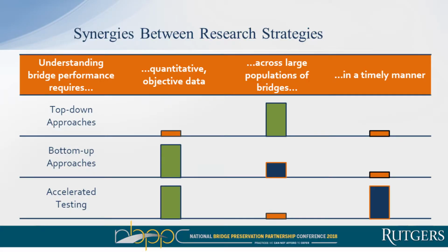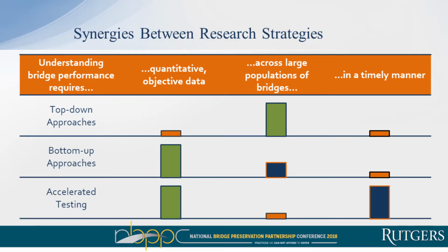All right, so this is my last slide, and then if there's time or interest, we can hopefully have some questions or discussions. This is something we showed before, but I'm adding accelerated testing here. And it's not perfect. There are a number of challenges we're going to have. One is balancing this. I can throw 18% salt on this all the time, and we get deterioration probably pretty quickly. Whether that's representative of what happens out in real life, I would argue is probably not. So being able to balance these different inputs and get realistic deterioration is going to be a challenge. We have to be honest about that. But it also provides a lot of value.